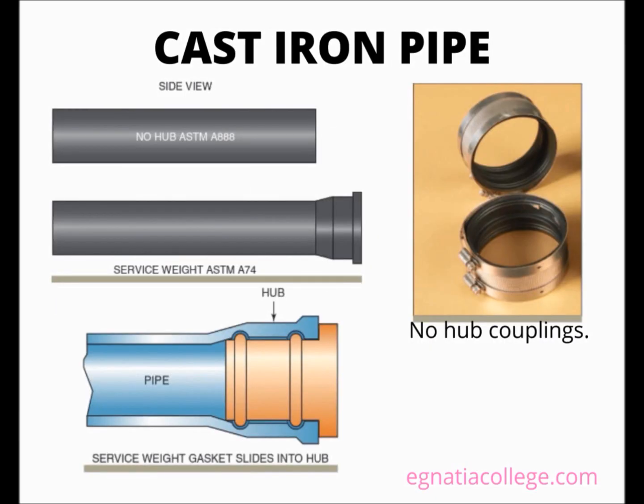Cast iron pipe. Cast iron pipe is often used in residential DWV systems for vertical installations to allow a quieter draining process in walls. The two most common types of cast iron used in a plumbing system are no hub (NHCI) and service weight (SWCI). They have different minimum sizes and methods of connection. Because codes do not allow pipes smaller than 2 inch to be buried below ground, and because SW is most often used there, 2 inch SW is the smallest size available.